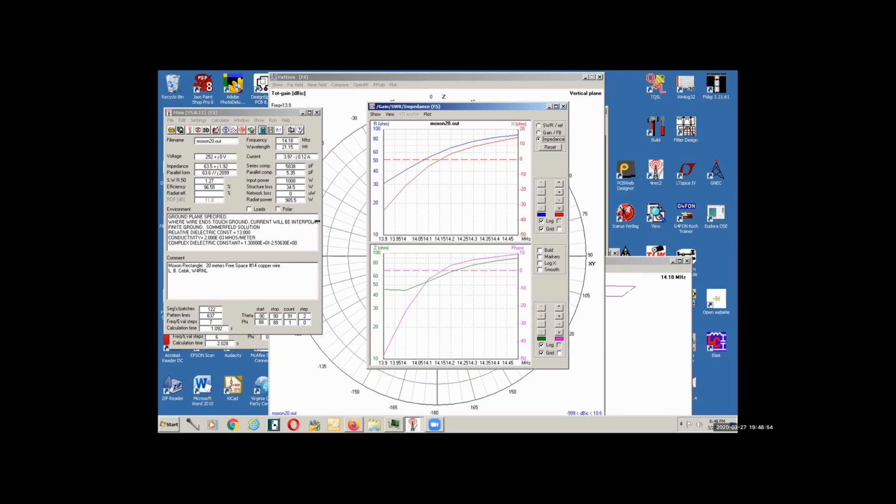What I have to show is, if we're dealing with something like this model here, where we have this Moxon up in the sky, it probably doesn't matter. The only problem we have to be careful of is where you have wires or radials that are close to the ground. And in the case of 4NEC2, that's why they provide this, quote, MININEC ground.